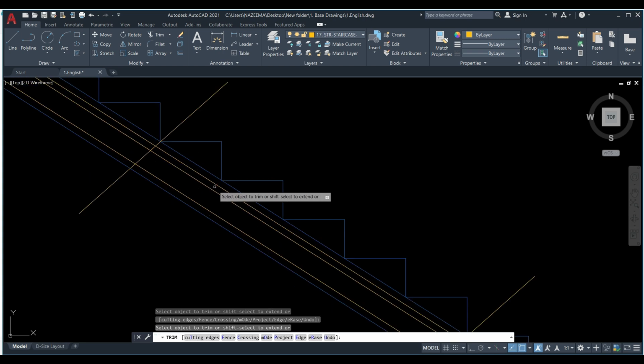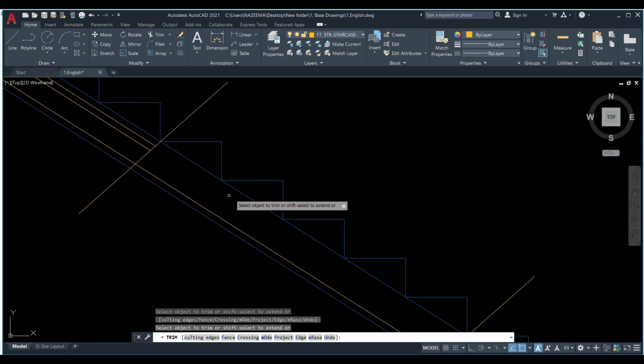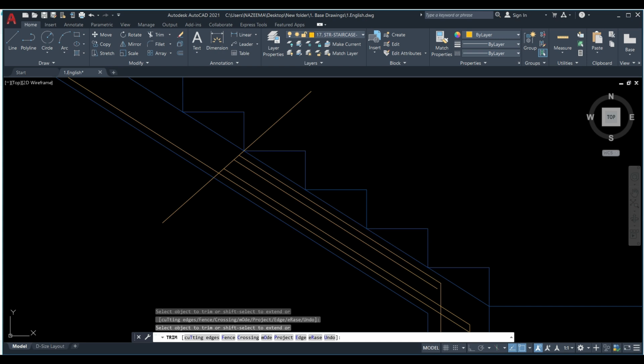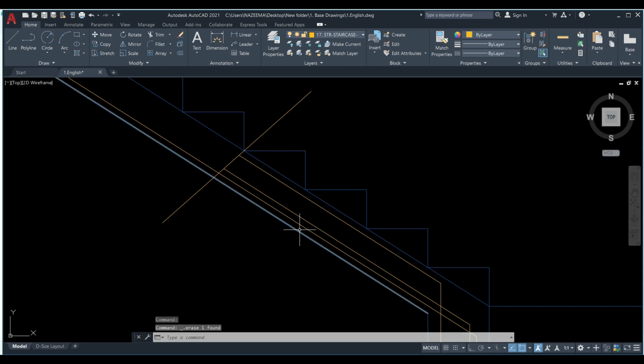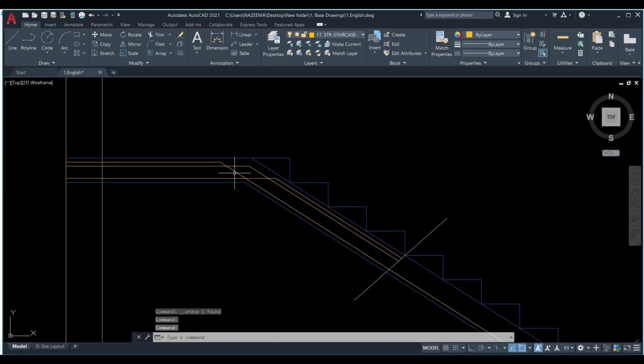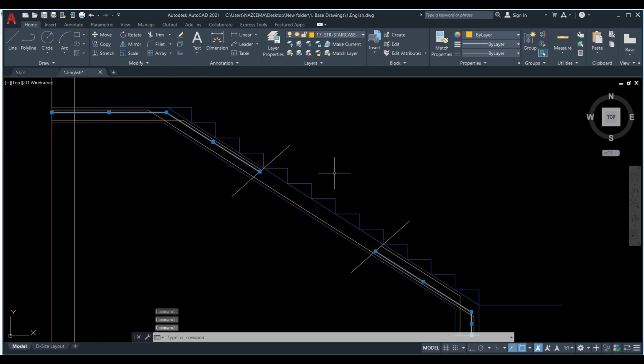The same thing holds true in the top mid portion. In the top mid portion, the tension is in the bottom zone. So here providing additional rebars makes no sense. Okay, and we have to remove this line also. This line. Okay, so second layer of additional reinforcement is provided over here, and it is provided over here. These 2 bars. Okay, if in case you delete them also, doesn't matter.